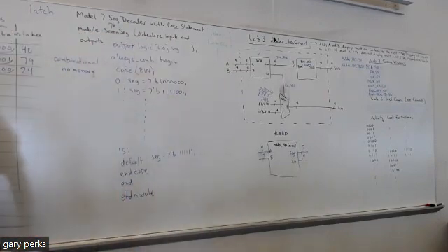And all 1s is going to shut off all the displays, right? Because if AN is a 1, that's going to make the output of this inverter a 0. That's going to put all zeros on the common anode. And if you have 0 on the anode, there's no way a segment can light.